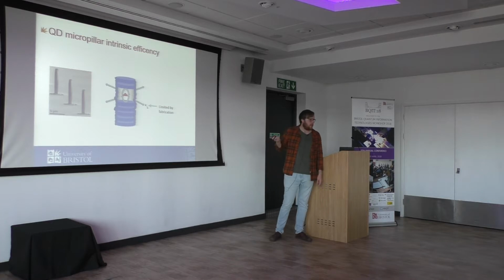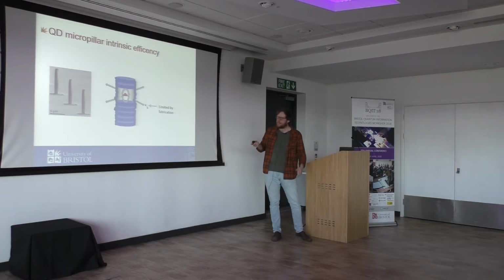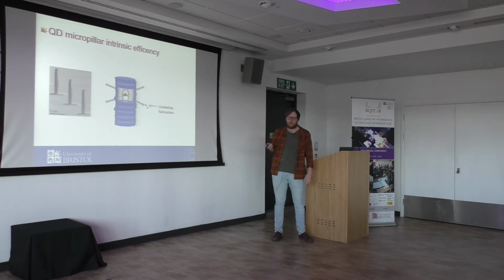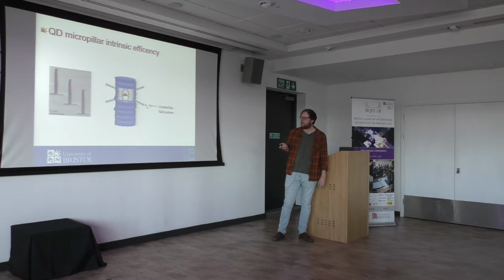This is limited by the way the pillars are etched, and to improve on that, you need to etch really straight edges down your micropillar. And it's quite a hard thing to improve, certainly in the short term anyway.